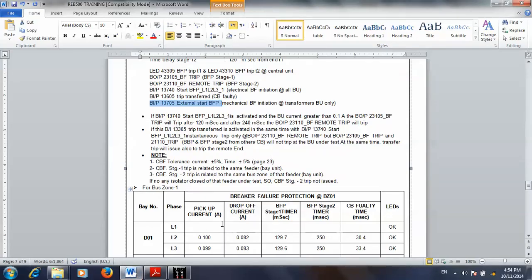by the same way you can test your function, but here without current. Here by circuit breaker status, one time you will give the binary input and the circuit breaker status is open, and the other time you will give the binary input and circuit breaker is closed, and you can inject this binary input through the Freja outputs, and in page 1 and page 2 you put the current and voltage, everything is 0, and only the test is through binary input.